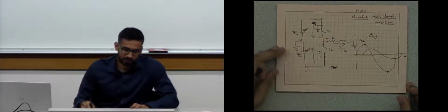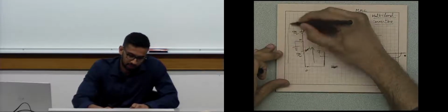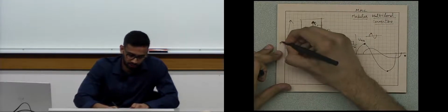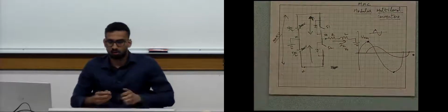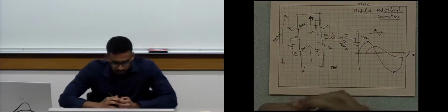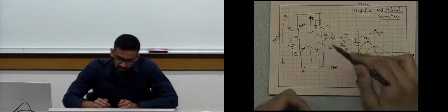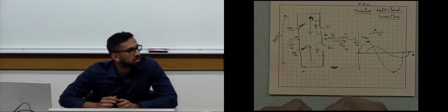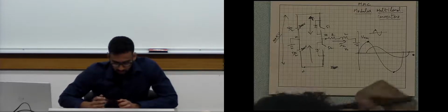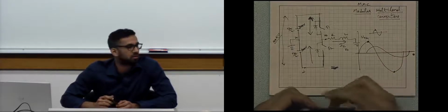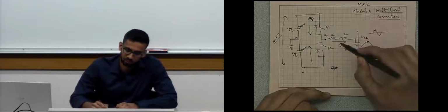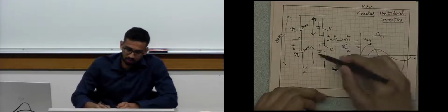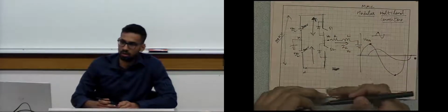What will happen if the total VDC is say 100 kV? Will this circuit as such be feasible? It's not feasible, because we know one of the switches is on at any time except during dead time. When there is dead time, still only one of the branches will conduct the current depending on the polarity of the current. The current is outward, this diode conducts. The current is inward, this diode conducts.